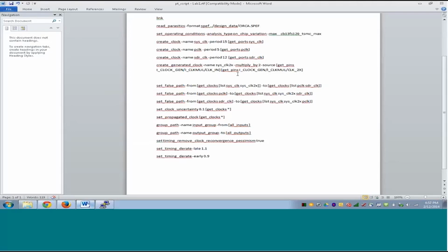Now in this case, I haven't specified any waveform. So for both the rise is at 0. For this, the rise edge is at 0, and the capture is at 7.5. For this, the rise is at 0, and capture is at 6. Since the waveform is similar in the sense they have 0 rise, the period difference is 3.